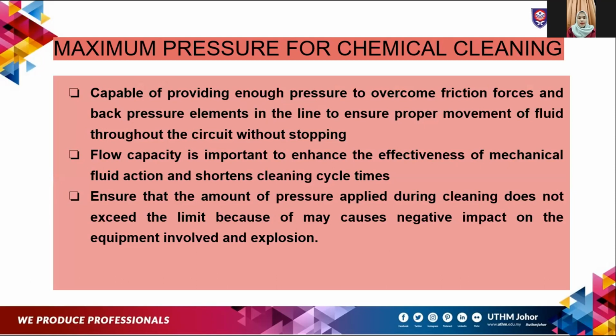First, the pump must be capable of providing enough pressure to overcome friction forces and back pressure elements in the line, to ensure proper movement of fluid throughout the circuit without stopping. For this first point, by identifying the pressure required for the chemical cleaning, we will ensure that the process goes on smoothly and we will achieve 100% chemical cleaning for our plant.